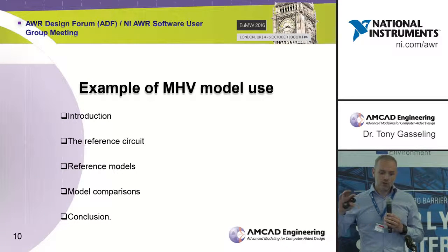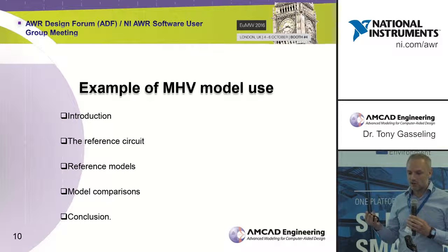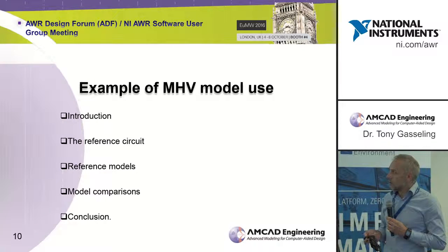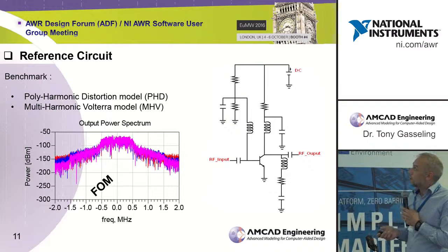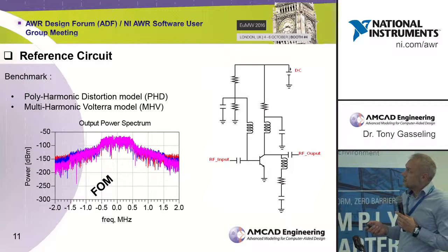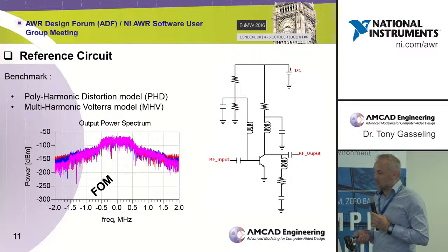So you can even use an amplifier which has been designed in a circuit simulator, and use the data provided by this circuit level simulation in order to extract your behavioral models. And this is what we have done here, in fact. We have done this exercise for a given amplifier. Here it was a common emitter amplifier, a very classic configuration. And the aim was to evaluate the improvement brought by this approach over a PHD model, especially when we are looking at the figures of merit of modulated signals.